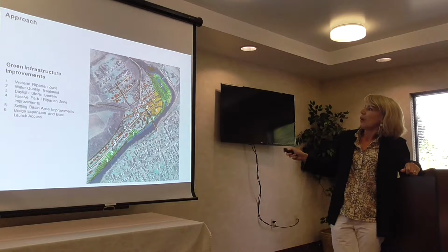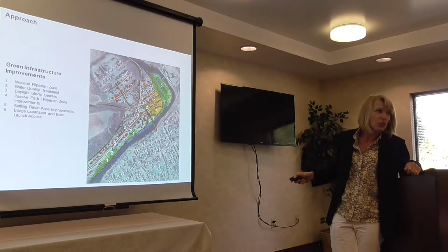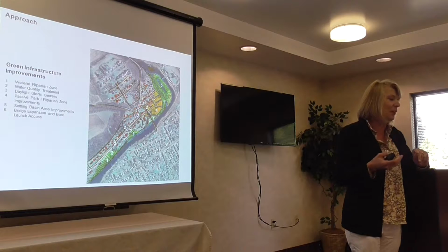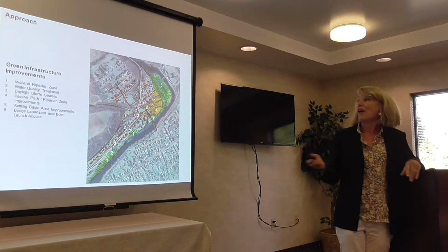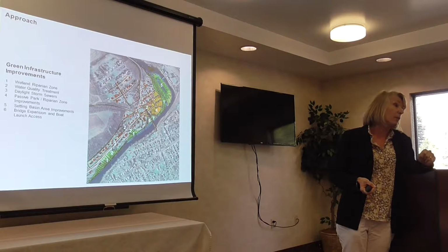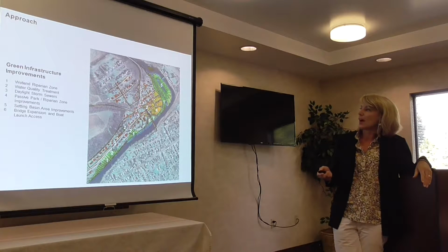Because of this low point, putting in your green infrastructure, your little stormwater BMPs, your rain gardens, daylighting your storm sewers and things like that are not going to improve those big storm events and the amount of flooding that goes through here. So that was kind of the big picture that came out of it.